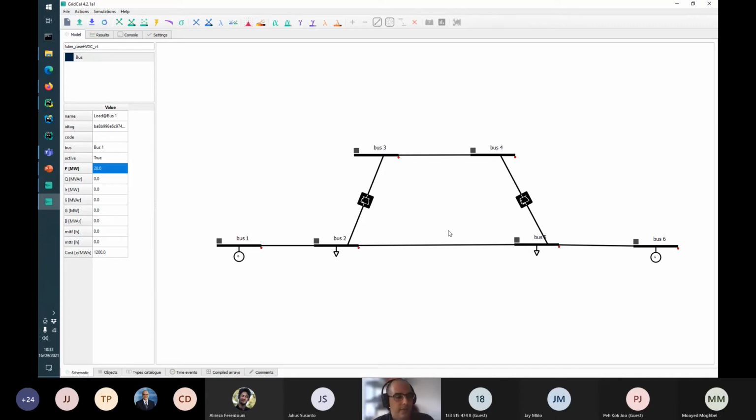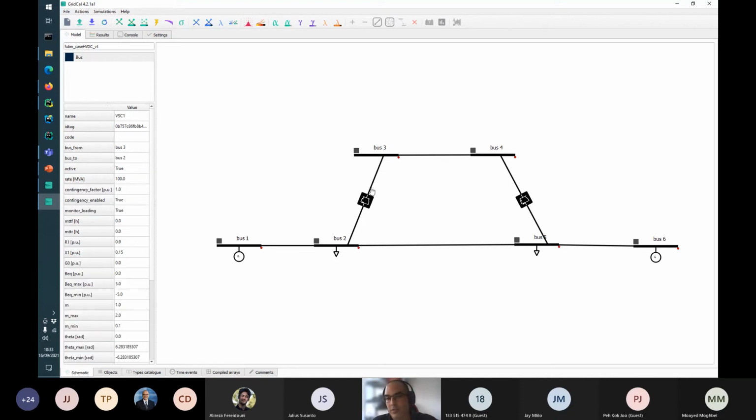So I called him and said, let's do a joint effort and try to improve your algorithm, make it even more efficient, and I will do that in GridCal. That is what allowed me to introduce this device, the VSC. The formulation of this person had 91 submatrices in the Jacobian, when, if you remember from the courses, the typical Jacobian has only 4 submatrices.